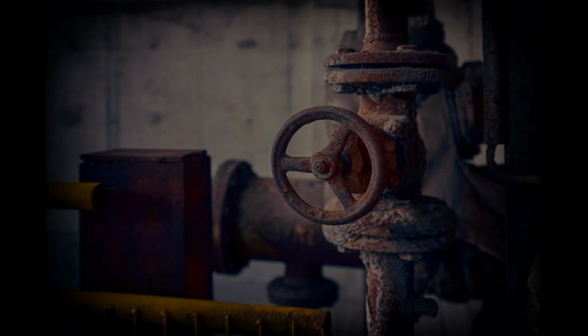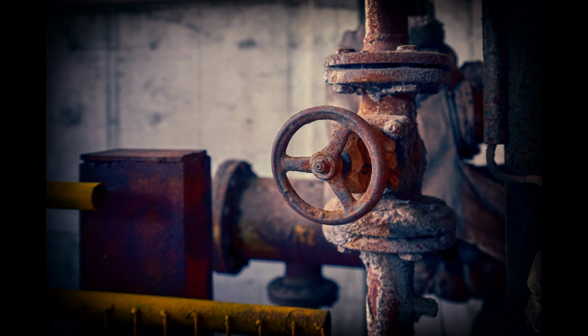While it might be easy enough to just extrapolate some type of asymmetrical distortion from this wave sort of sagging through the device, even if the transfer was completely linear, I did perhaps gloss over some more fundamental components of the tube's clipping behavior, things that further enhance this asymmetrical output concept, and I will cover some of those now. The positive half of the signal is susceptible to grid clipping, while the negative half is susceptible to cutoff clipping, and we will talk about the latter first.